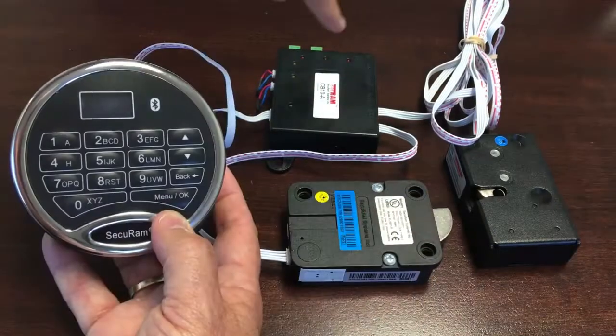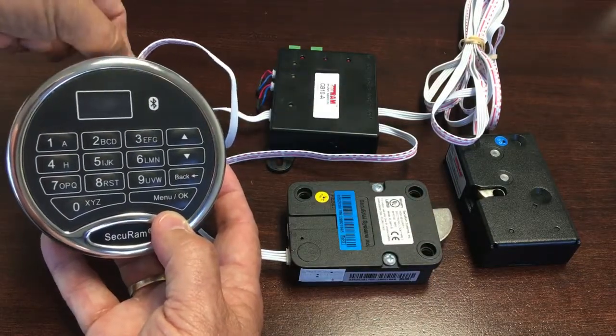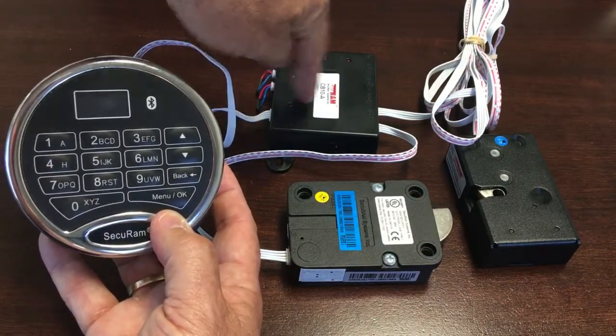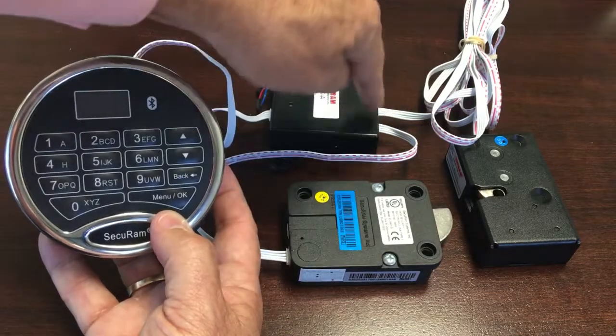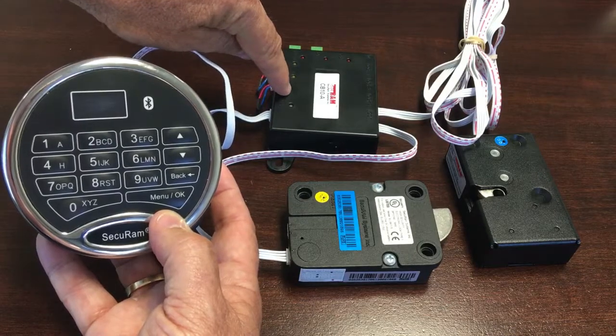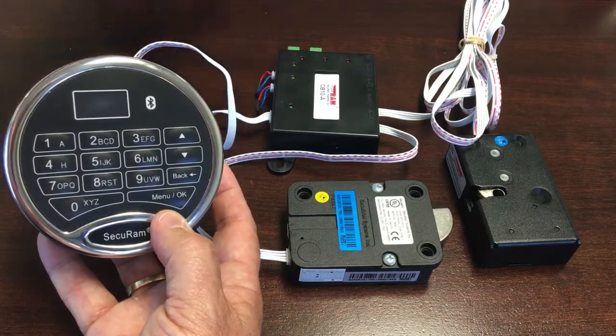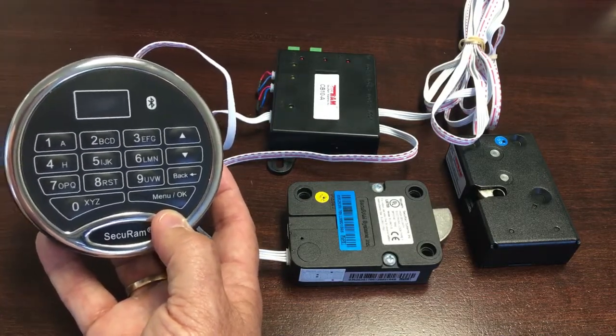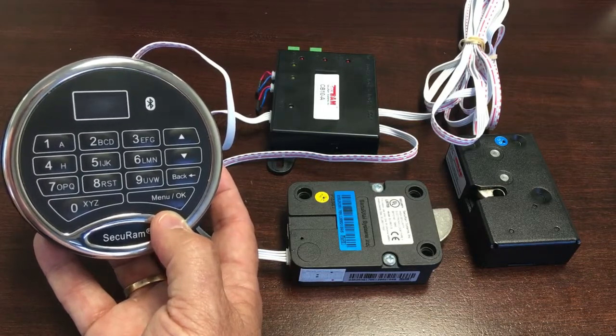And those two are connected by this junction box. So the keypad or entry pad is connected to the junction box. The junction box connects lock 1 and then lock 2. And this junction box is also a Duress module, so it can be wired to the alarm panel in order to send a silent alarm in case of duress.